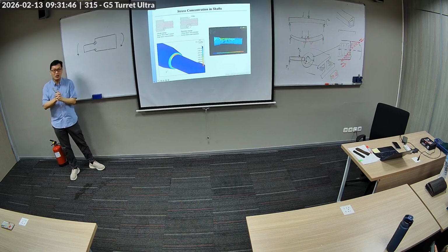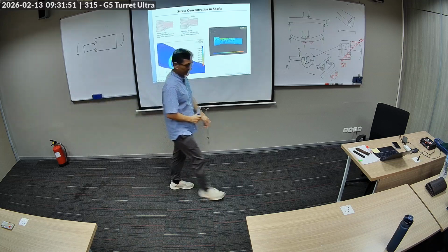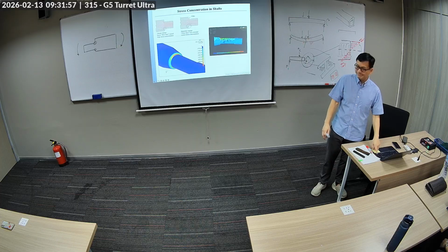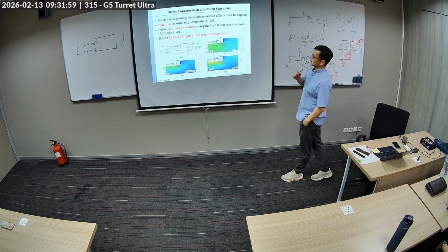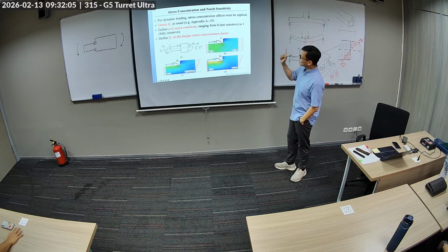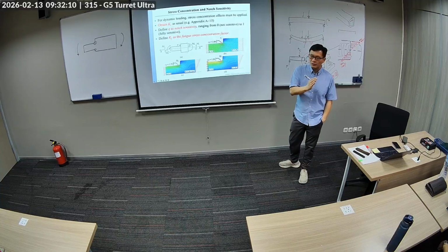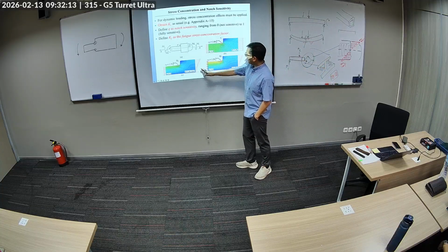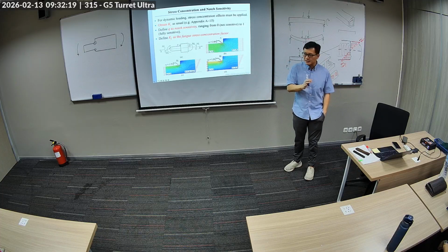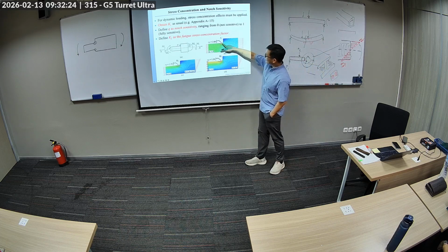In every shaft analysis that we're going to do, we're going to deal with the critical points only. So, yes, the diameter of the shaft is not that big of a deal. The radius is. So, for dynamic loading, stress concentration effects must be applied. In fact, this is going to be the focus of the calculation. Now, this is a simulation, again, finite element analysis, where you do computer simulation, basically, with different radiuses.